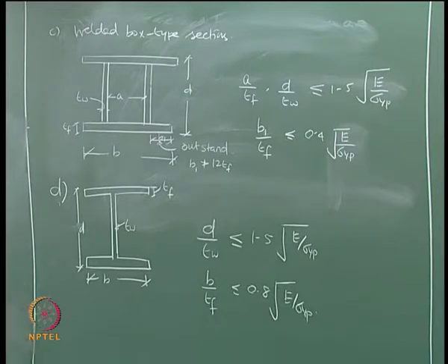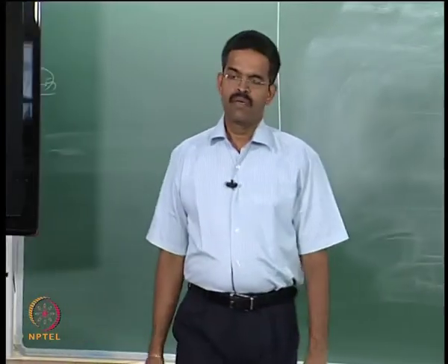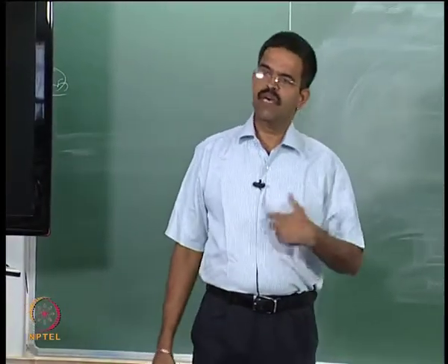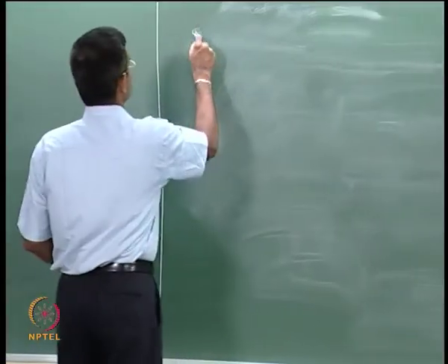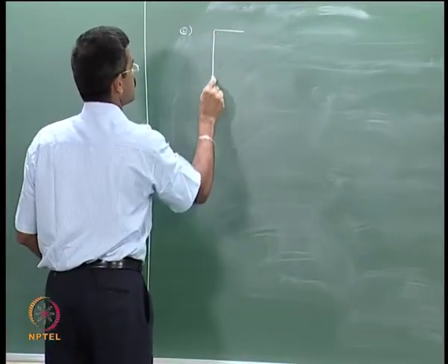So, it is important for us to know how to establish that my section remains compact, because compact sections will not have buckling effect acting on them, and we can directly deal with the yielding load. Okay, that is why we are discussing this. The next common section, of course, is the channel section.